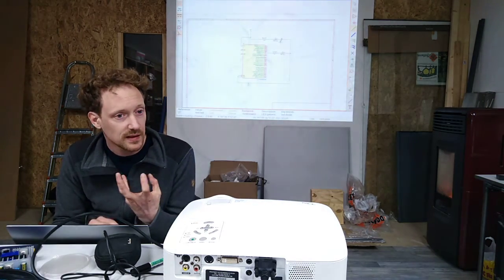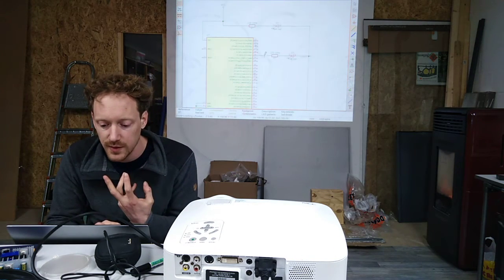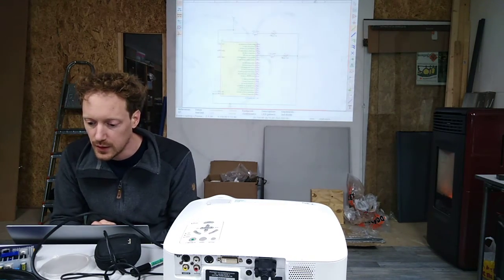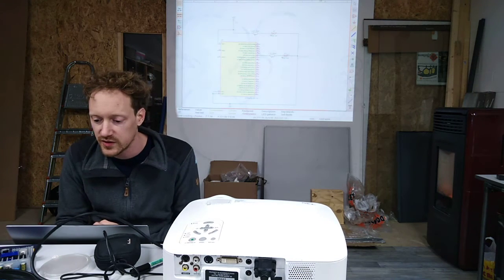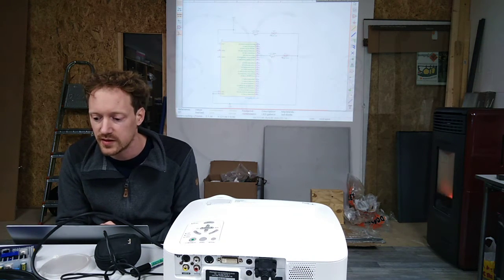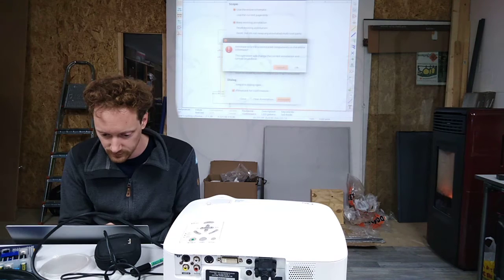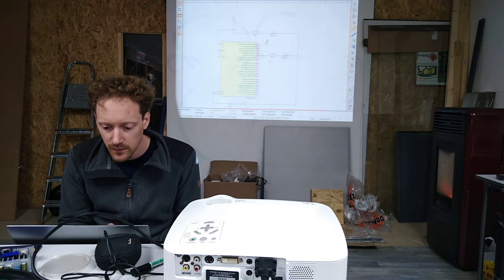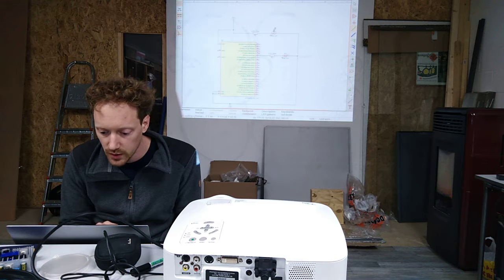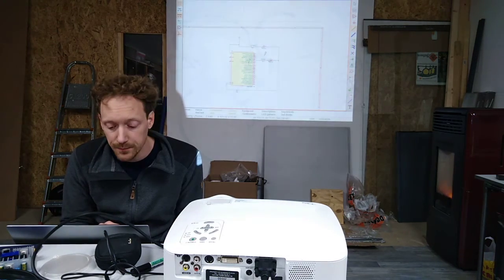So now we can automatically assign, so this is not a full schematic, but let's just continue with this. I think you get the basic idea. So now we can annotate all those components automatically and give them a unique name by pressing this button, I believe. Yeah, annotate schematic components. And we just press annotate. Annotate only or the entire, so yeah, I'm just doing OK. And now you can see that D1 we have here, and D2 and R1 and R2, everything has now a unique name.